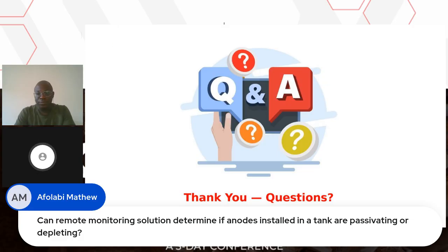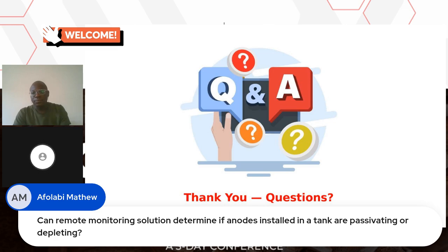Let me just give you an example. Let's say we measure a corrosion potential for a particular line, and by the way, corrosion potential is not a big deal. It just means that on a normal line which is not protected, you measure the potential with a reference electrode. Put a cable on the line to a voltmeter, and then from the voltmeter to a reference electrode, and put the reference electrode in the environment. With that, you can measure clearly what the corrosion potential is. So our corrosion potential is just the voltage of the material.